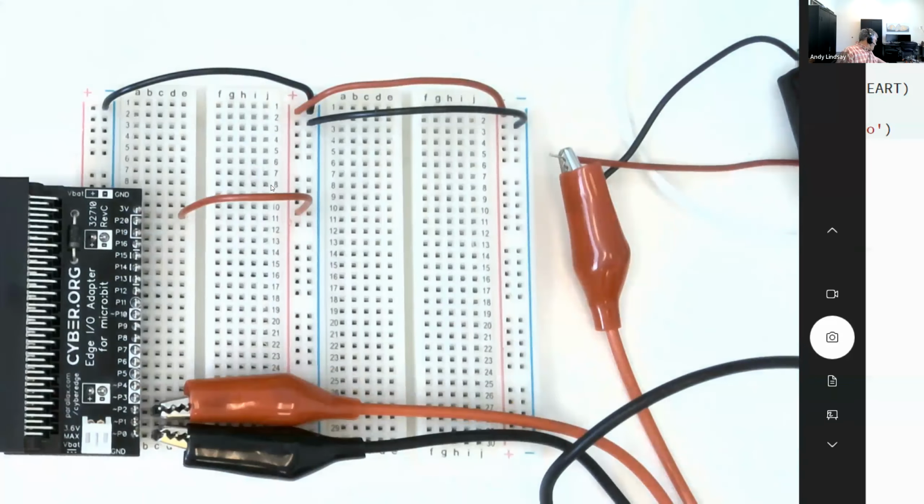See the blue stripe here that's vertical on your board? Any socket next to that blue stripe should be essentially ground or 0 volts. And so we're plugging our black probe into any socket next to the blue stripe at the far right of our breadboard.